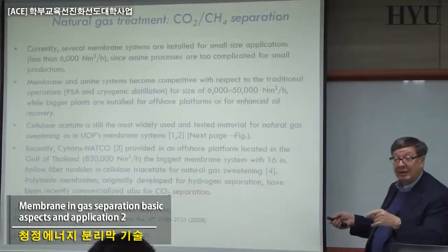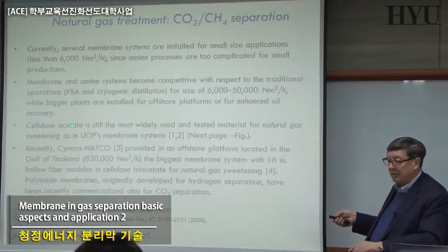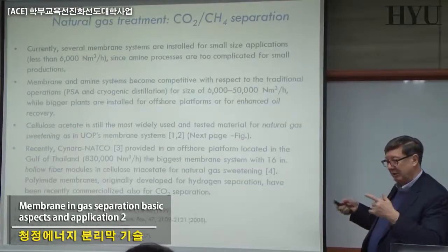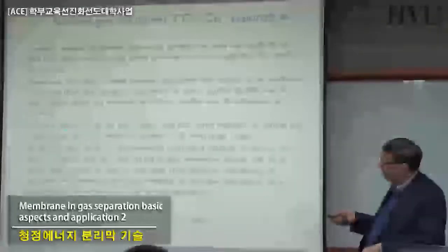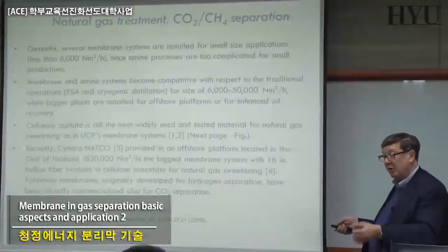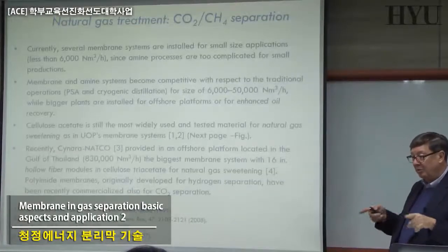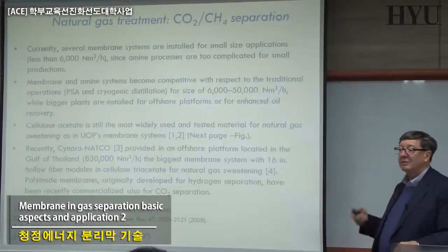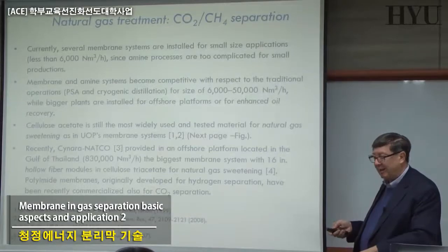People found one day, made a patent on how to have cellulose acetate always wet with some addition, I don't know, ethylene glycol, etc. Still today, we have a membrane for gas separation based on cellulose acetate, which were the initial RO membranes readapted to work in a dry atmosphere, no wet, and so solving the mechanical properties.